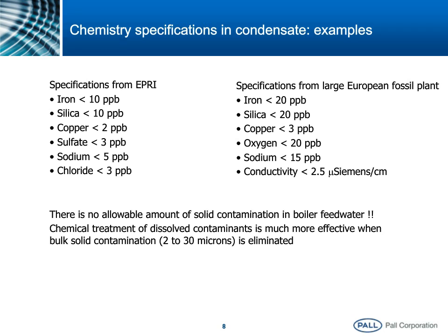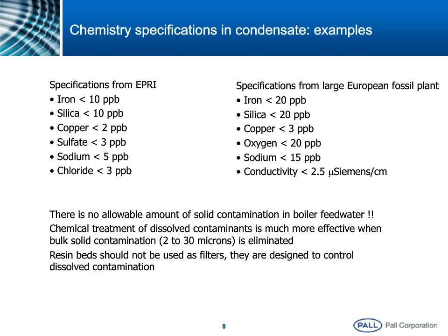It will be less cost effective. It will cost more in chemicals. It will be harder to monitor, harder to stabilize, because really this bulk solid contamination in the system, if it exists and is allowed to remain, will kind of throw everything out of whack in terms of how the chemistry of the water works. And the last point to remember is that the resin beds that may be present in the condensate loop are not there to stop particles. So they're not filters, and they should not be used as filters.